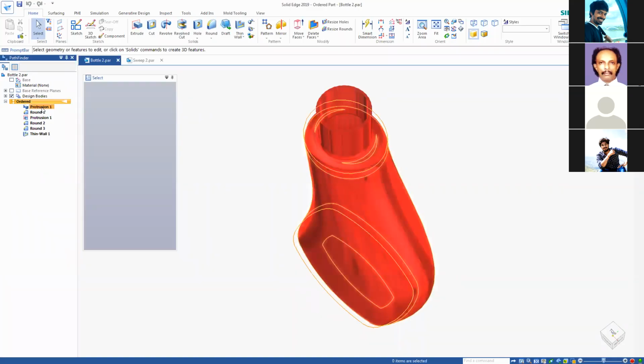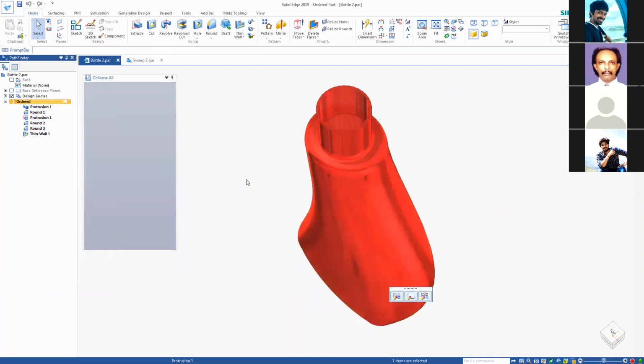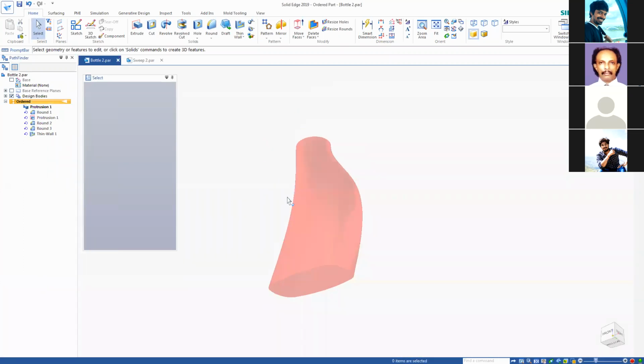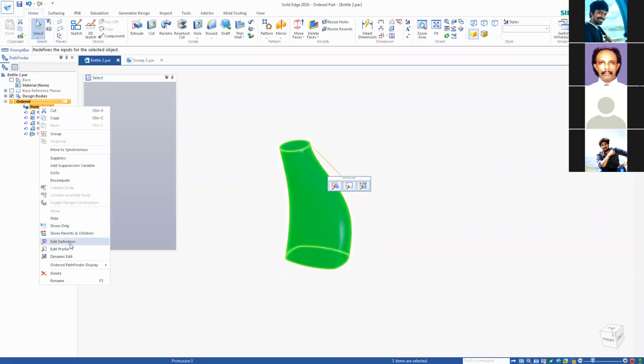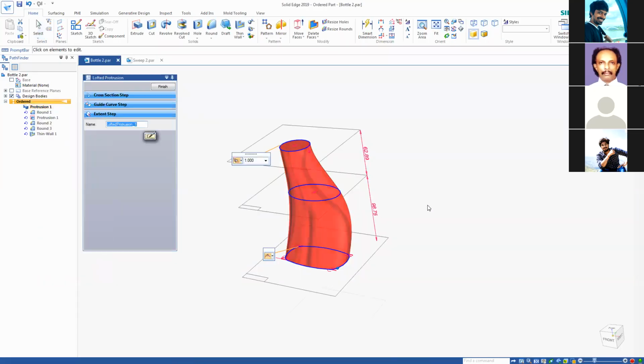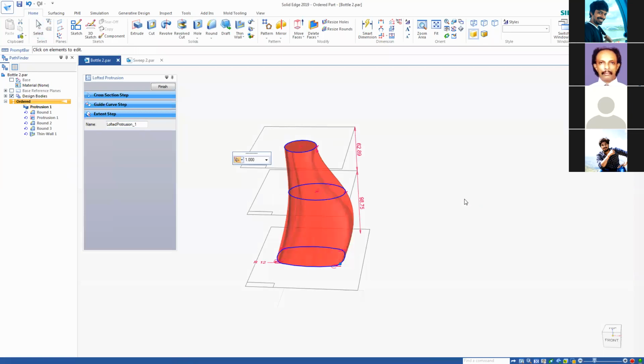Now if you go to the Pathfinder, you see if I go back and start, this is how you started, right? All my sketches are built in, so you can't see them. All I had was maybe this space, you can see a kind of sketch-like thing, and also maybe there. It's a loft command. You see, this is the loft command. Right click, and if you say edit definition, you will be able to see that. Can you see the three sketches at three different locations?